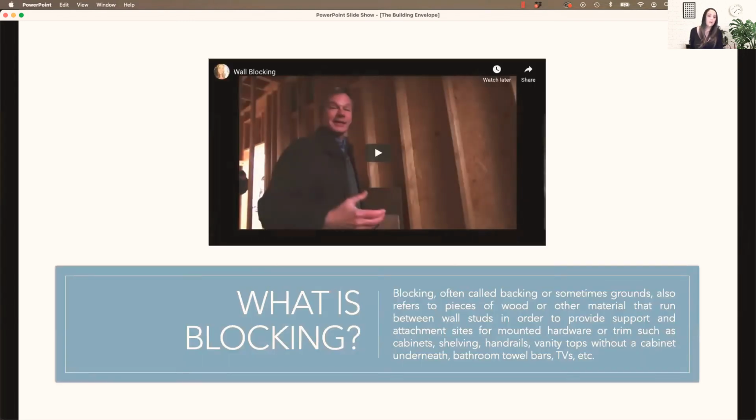So we were talking about locating studs, and especially in kitchen design, you will be installing kitchen cabinets in your designs, and those need to be secured to a stud, or they need to screw into a wood wall. So if you can't find a stud, or a stud isn't available where you want to hang something that's heavier, like a cabinet or other millwork item, even artwork sometimes, heavy mirrors and things, you'll want to secure those to a stud.